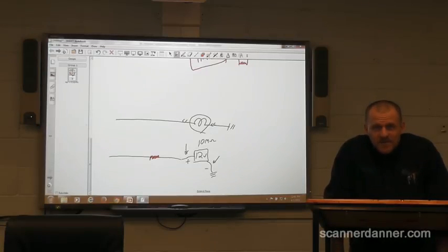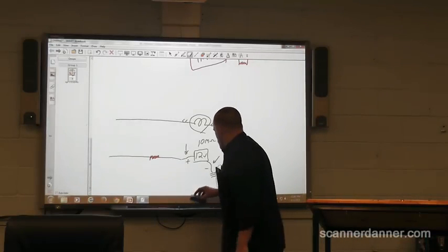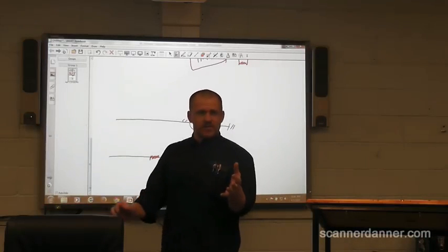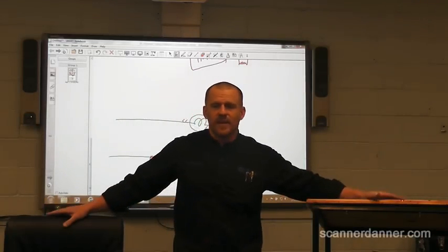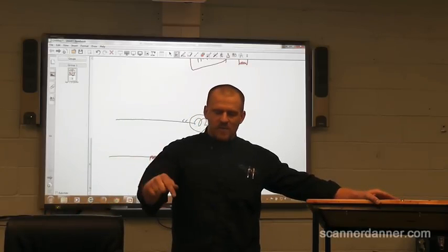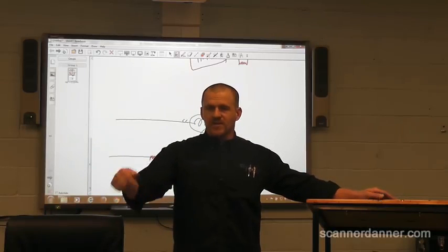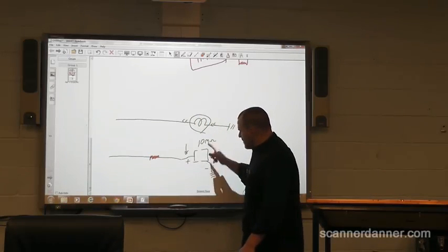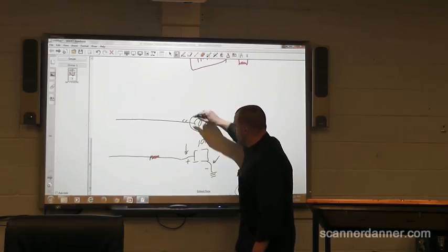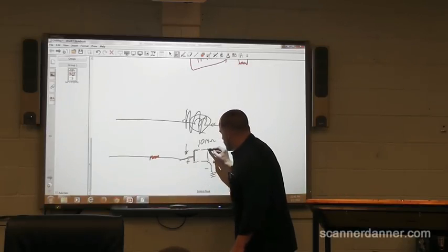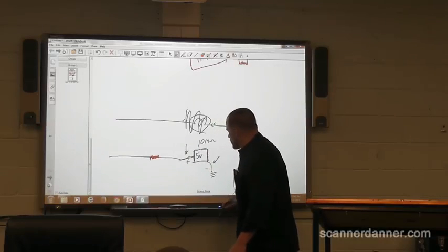Let's see if this makes sense. I connect to that circuit, and it would seem to contradict what I said yesterday, which is the circuit has to be loaded to see a voltage drop. That would be the point. And there are certain circuits that have so much resistance that your voltmeter itself will draw the voltage down when you connect to it. So in this scenario, that resistance is so bad that even this 10 mega ohm impedance meter, remember the bulb's disconnected. There's nowhere for current to travel. As soon as I connect my meter up to this, it reads, let's say 5 volts.